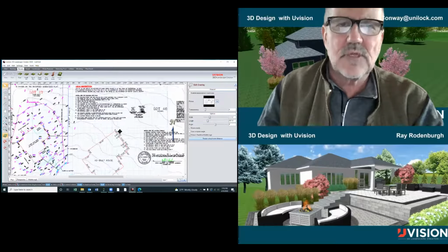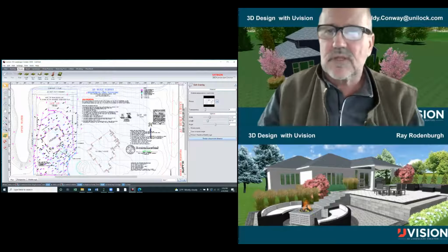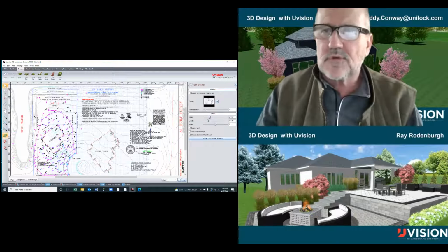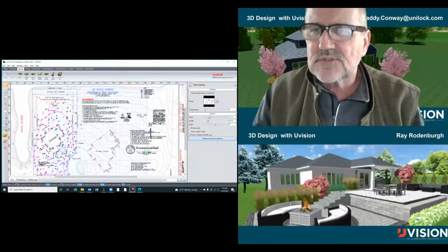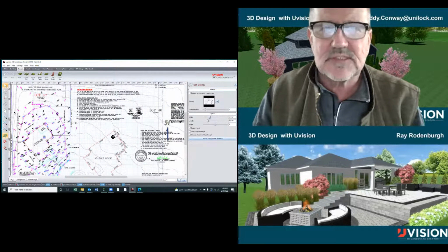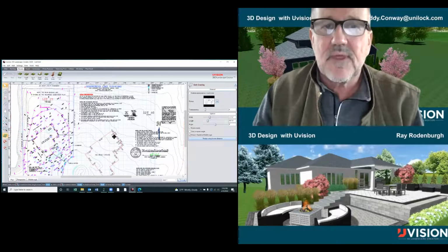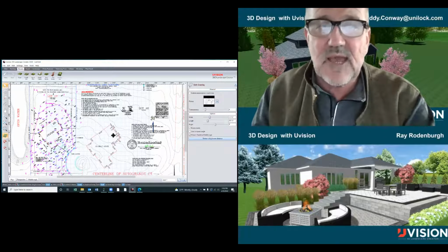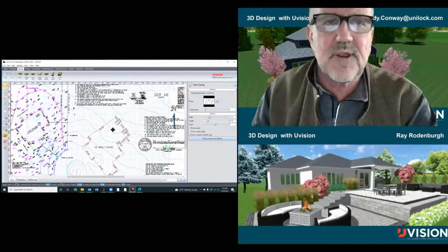Now my drawing is scaled just by 1 click, and it's this button here. When you import it, click on resize using known distance, find a distance on screen, and that is how you scale your drawing, as we've done in the prior classes.